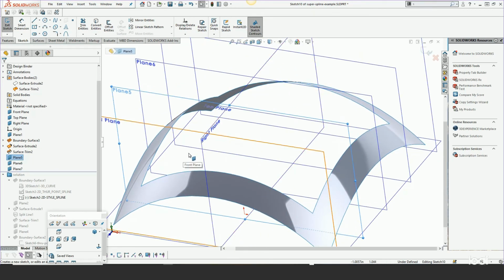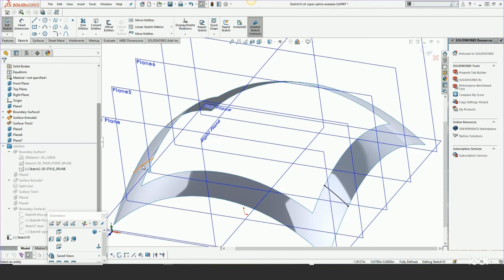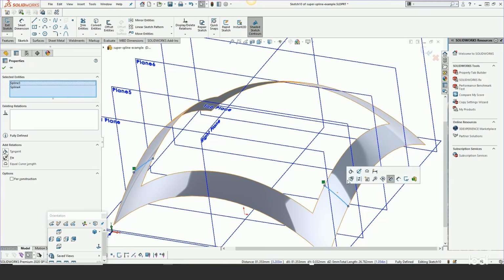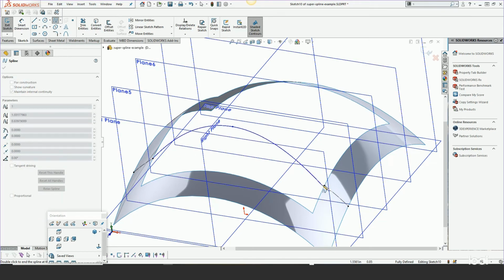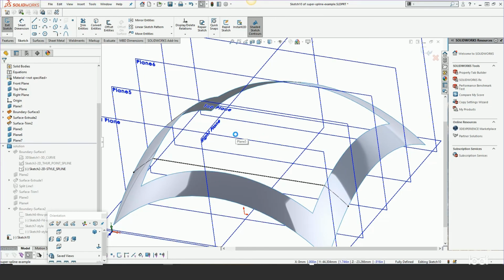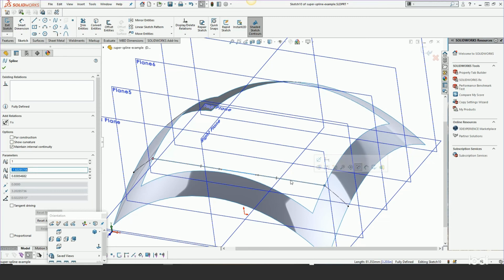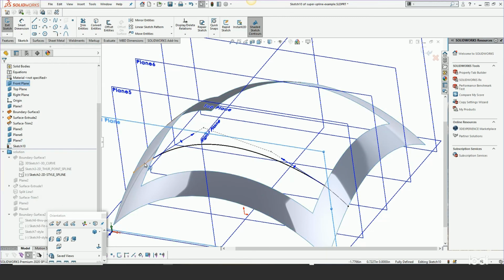And immediately what I do when I'm building what I call bridge curves is I'll use the intersection curve to get some references. So I'm picking this outside existing face and laying down this intersection curve only as reference. So that's why I go immediately to construction, and now I can create my Thru-Point Spline. And remember, I don't like to use 3 points, so I'll just drag these up, make tangency here,